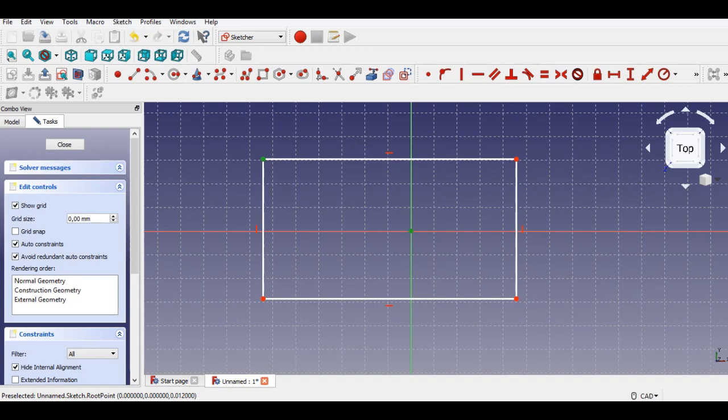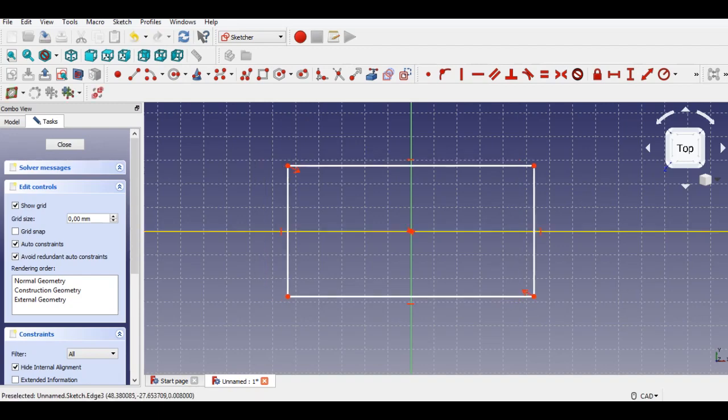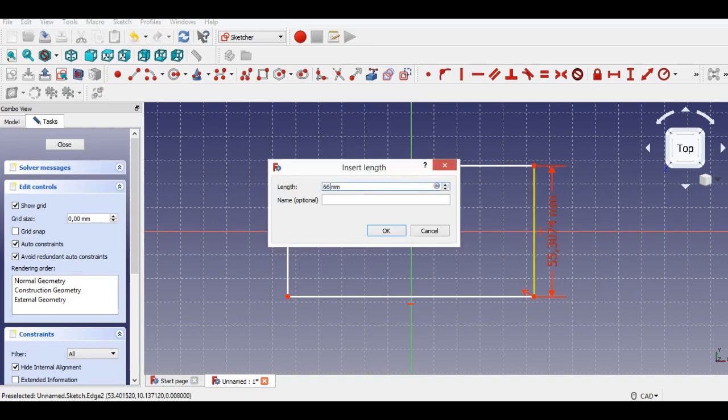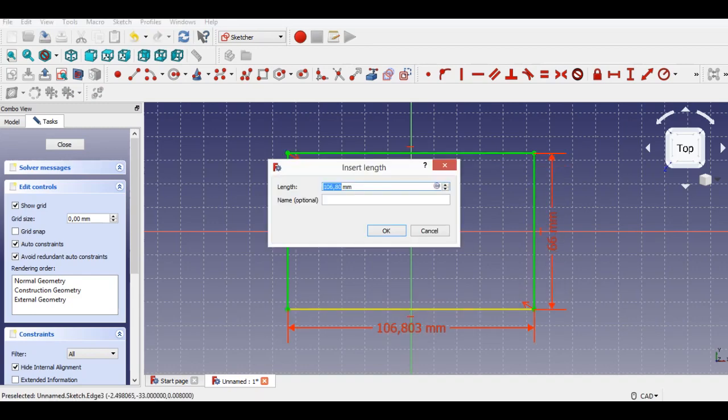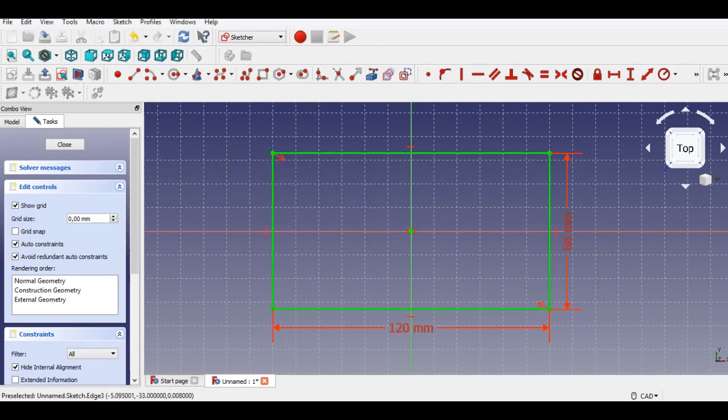And we draw 4 circles by using the copy button. To copy a circle, first press and hold Ctrl, select the circle and the Y-axis. Now take off your finger from the Ctrl key and select the copy button from the left top side.